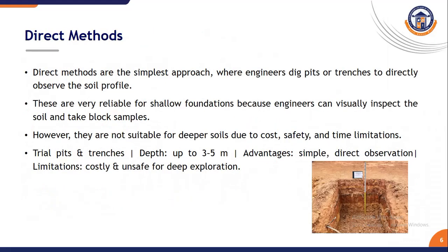The first one is the direct method. It is the simplest method. We dig pits or trenches and observe the soil layers directly. They are reliable for shallow foundations because the engineer can see the soil and even take block samples. However, they are not suitable for deeper exploration, as they become costly and unsafe beyond 3 to 5 meters.